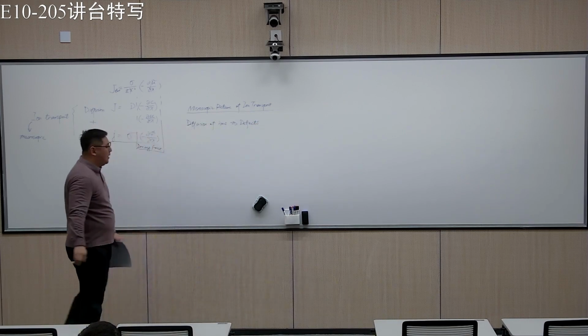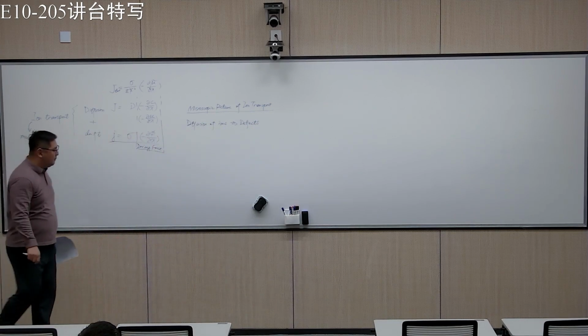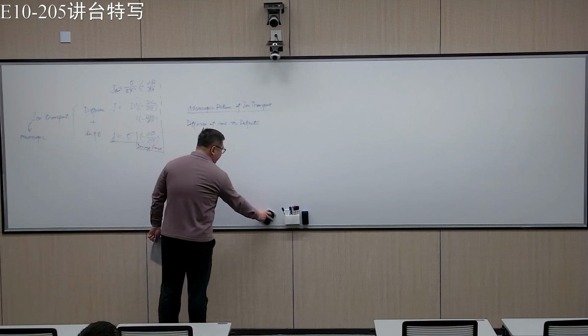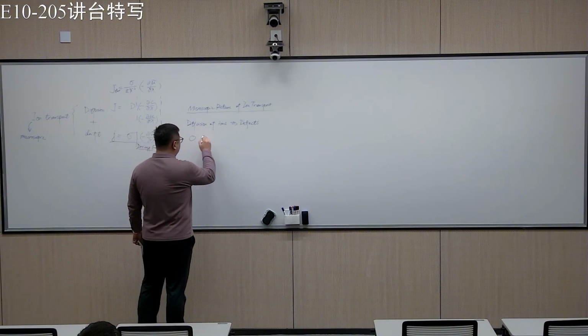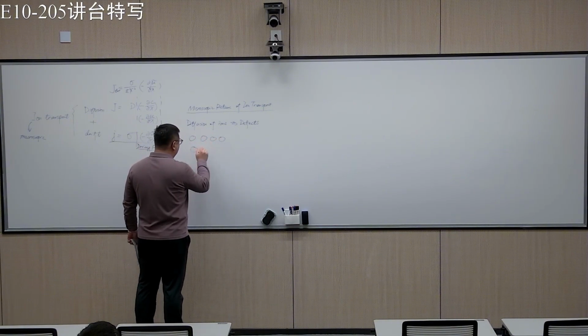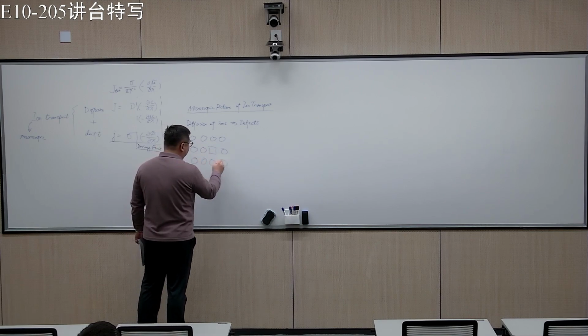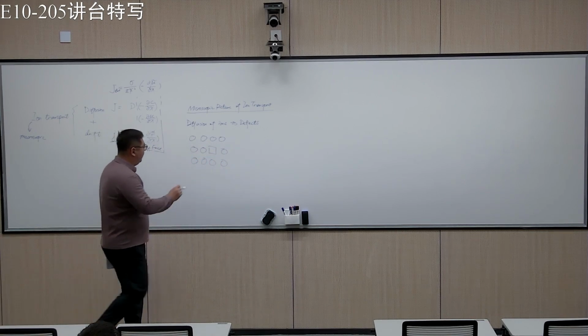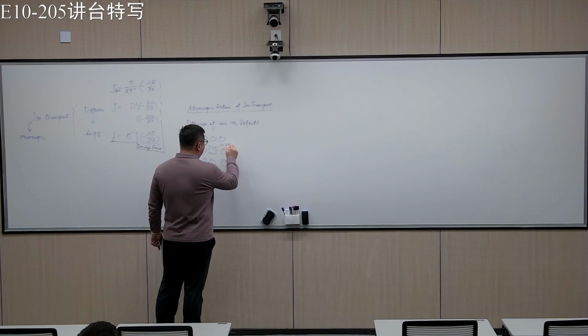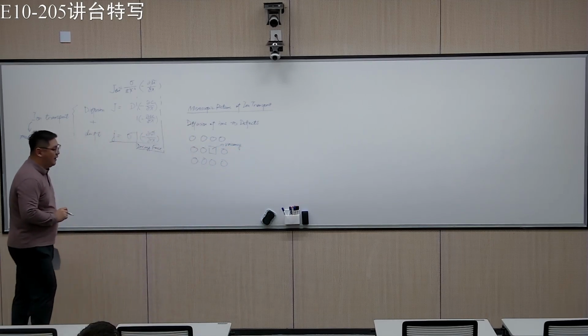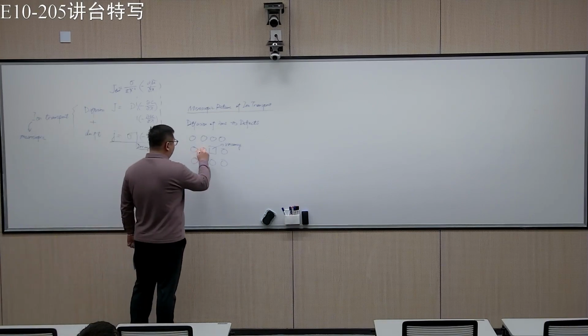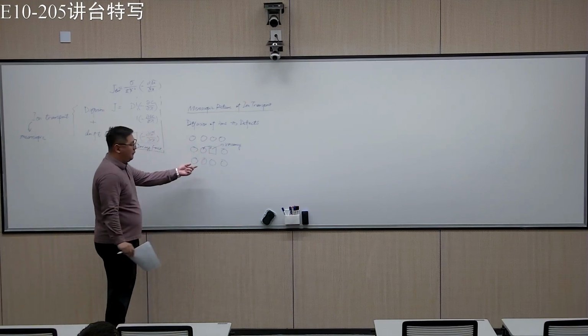So if you think about the atomistic picture, there are essentially three different kinds of mechanisms. So the first one is that you can have, for example, vacancies. Okay. So basically, you have a vacancy. So you can imagine that the ions basically jump from the regular site to the vacancy.